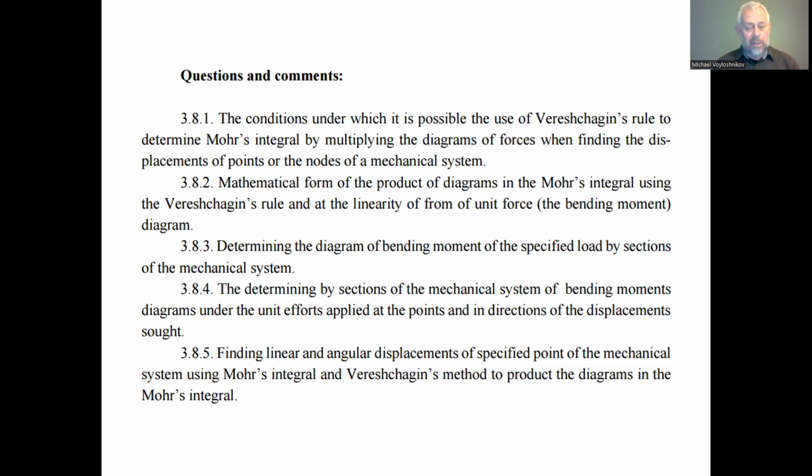3.9. Then plot the bending moment diagrams of the mechanical system under the unit efforts applied at the points and in the directions of the displacement sought. First we have to coincide the limits of determination of the Mohr integral with each element of the mechanical system.